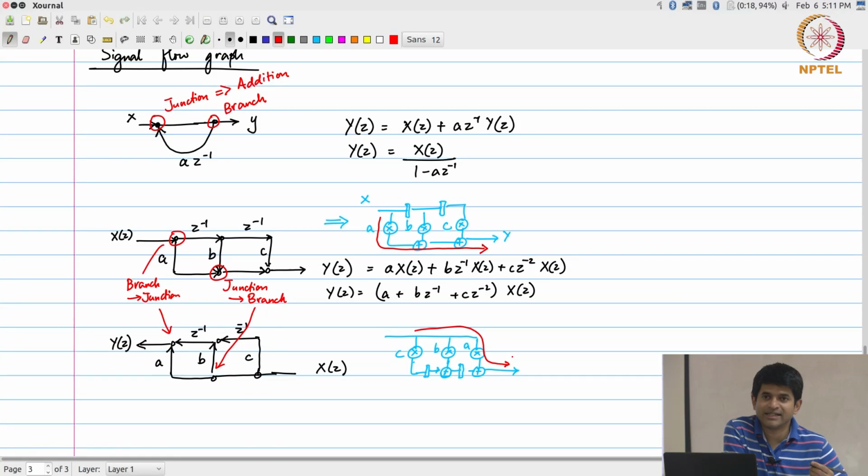Fundamentally, it has been changed in such a way that after every adder there is a register. So the output of the addition basically goes into a register, and in that way effectively what we are saying is that no matter how many taps this filter has, the critical path is always going to be restricted to 1 multiply and 1 add.